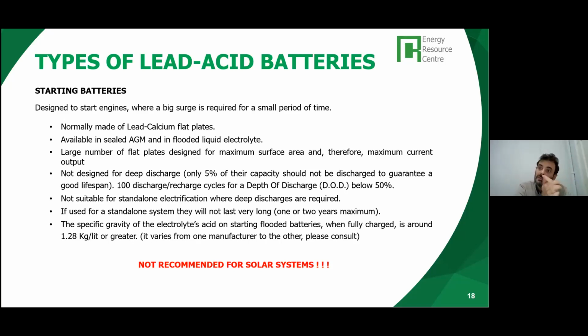In off-grid applications, we would probably like to have electricity service throughout the night, so that's at least 6 to 8 hours. So this type of battery is not really recommended for solar systems. When we do our specifications for our projects and programs, we have to make this very clear. These batteries are not designed for deep discharge. Only 5% of the capacity should be discharged, and they age very quickly if we go for deeper discharges.